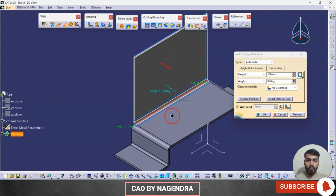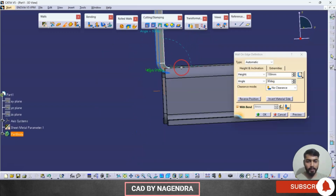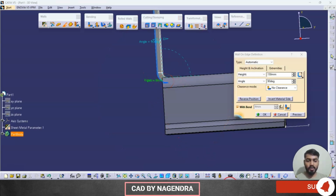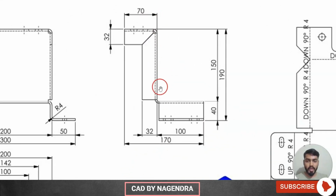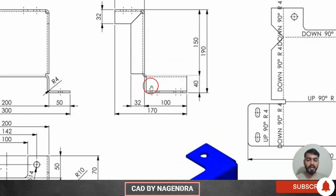So next we need to observe, after giving this height of 150, we need to check this bend, whether material should start from inside or outside. So let me open this and check this. Here you can see we have given this edge flange which is having height of 150. Then if you observe properly, up to here we have given length of 96. But from here with a distance of 100, it means this gap distance is 100 minus 96. After making a gap of 4 mm, we need this extra edge flange.